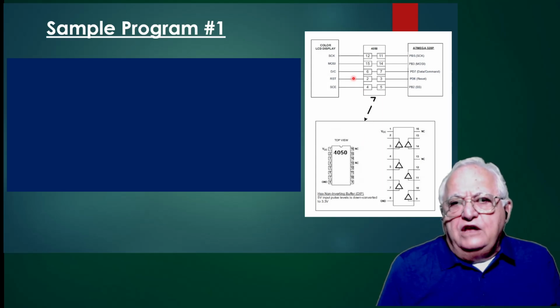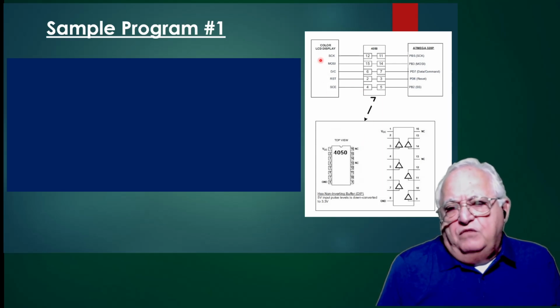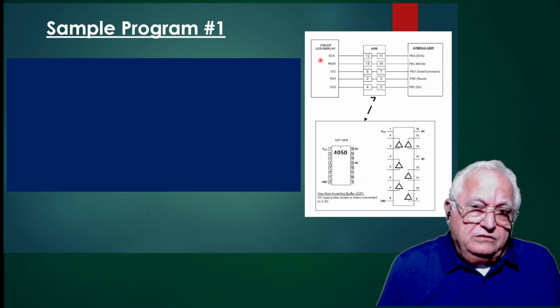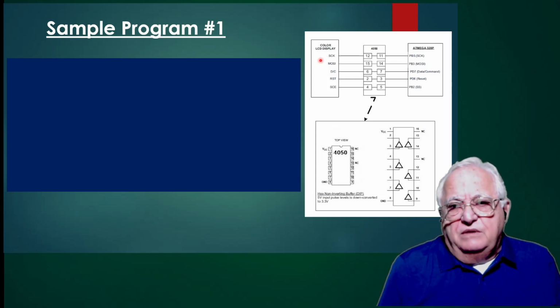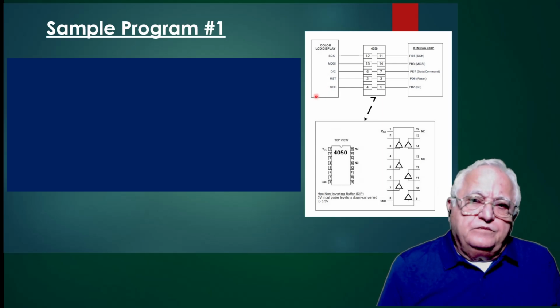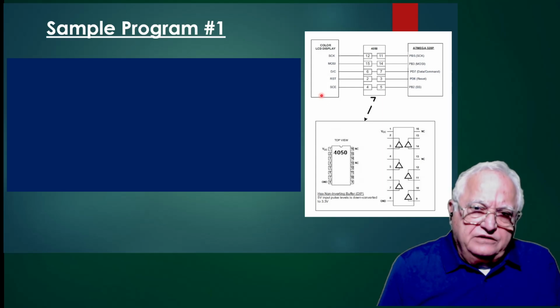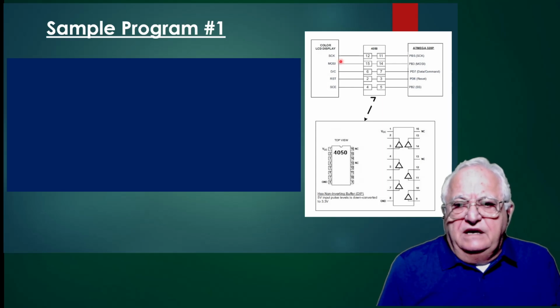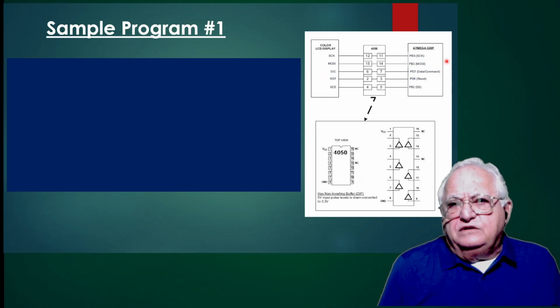Most of the displays are 3 volts, I mean, the ones that you hook up to or you buy in Amazon or someplace. So I provide 3 volts, and then I provide the level shift to 3 volts because your ATMEGA is at 5 volts.